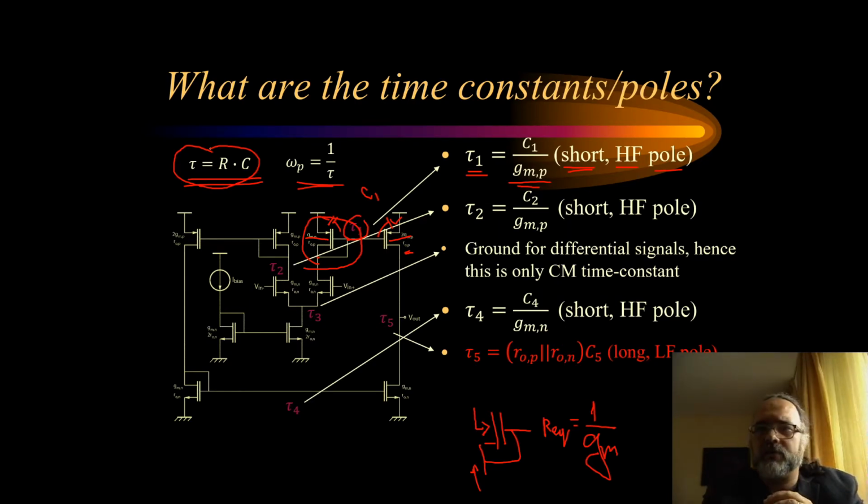If the time constant is long, we will charge the capacitance slower. The time constant will be short if the resistance is small. This means that we charge a capacitance through a very small resistance, so we can charge this capacitance with a lot of current. Hence, the capacitance will be charged quickly.